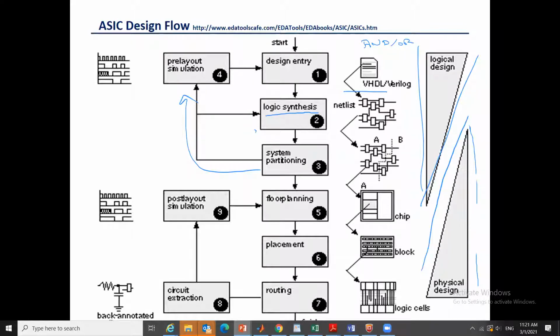Once we settle down, this then goes to the physical design. The physical design says, great, you have all of these units. Of course, I cannot put them sequentially connected to each other. My chip will be very large. And they are not all uniform, although I try to make them all as regular as possible. But I want to put the most optimal floor plan with the best clock distribution and all of these optimization problems, where we have specific tools. This is where the design automation engineers play their role.